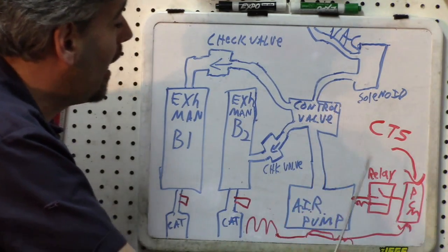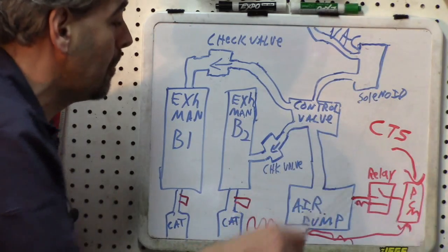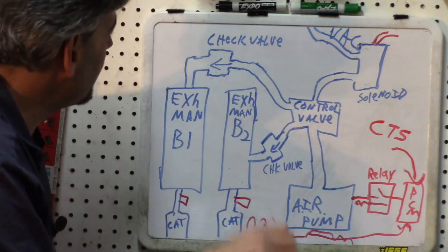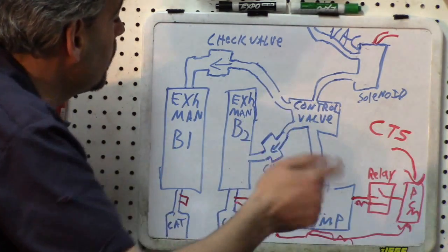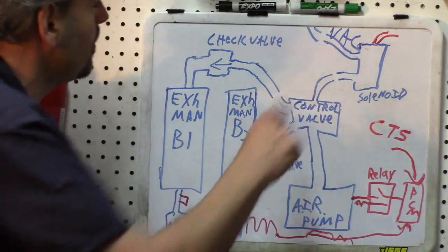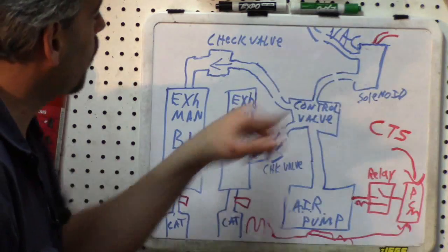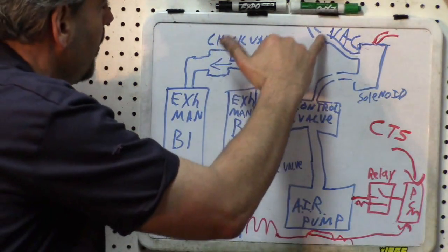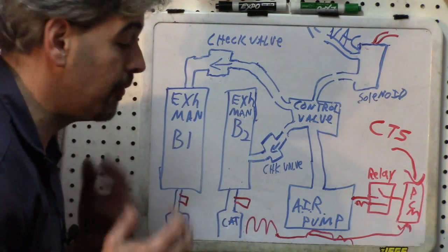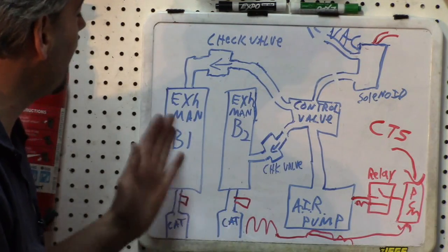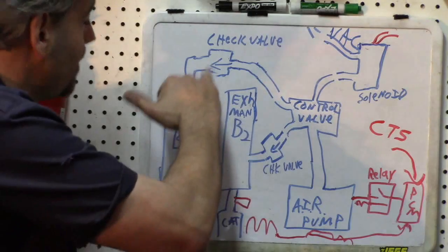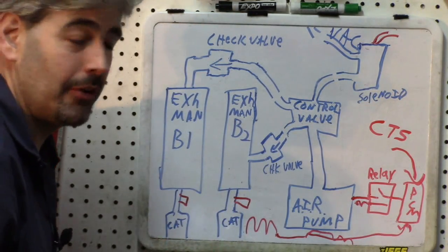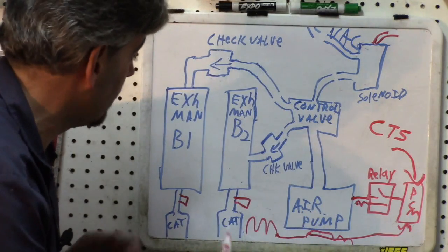After that, a lot of times an electrical problem or a solenoid problem could be the cause. I usually find it easier to test the solenoid, and after that, the electrical. Obviously, it goes without saying that any kinds of leaks or opens here, particularly with the solenoid, because those are going to be very thin tubes, would cause failure of the control valve to operate. Also, you might have vacuum leaks from the system if this occurs up here. Another possibility, the check valves very often develop a lot of carbon in them, so they may either not have the one-way direction function or may be blocking airflow. I've definitely seen a lot of carbon buildup in check valves. Other than that, that pretty much covers it, so you know kind of where to check. But certainly the air pump is a great starting point.